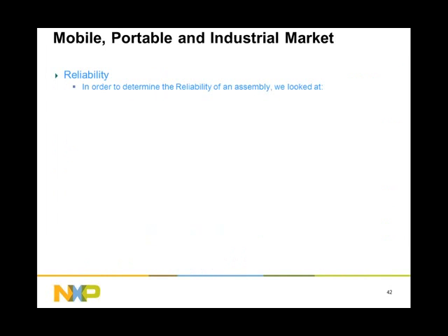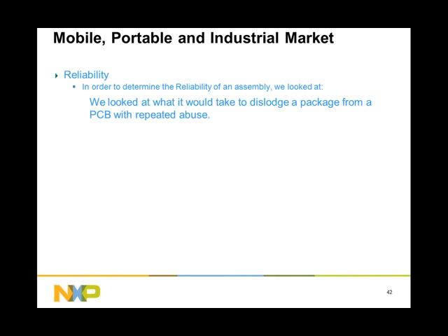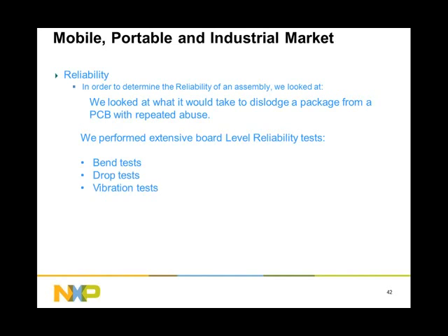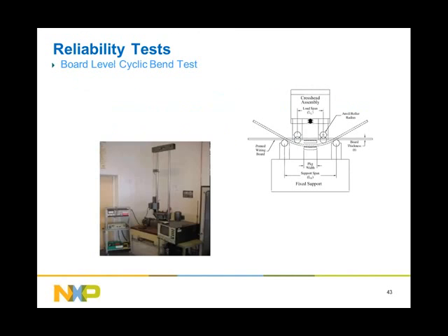We also looked at the reliability, and in order to determine the reliability of an assembly, we looked at what it would take to dislodge a package from a PCB with repeated abuse. So we performed extensive board-level reliability tests. We did bend testing, drop testing, and vibration testing.